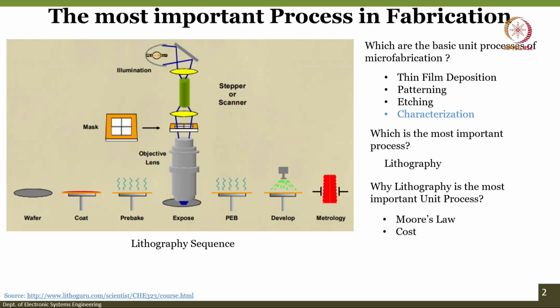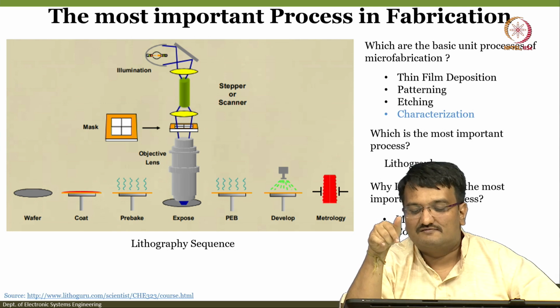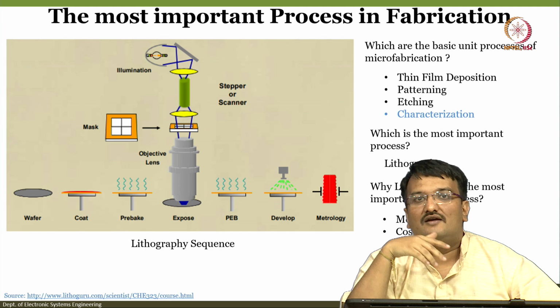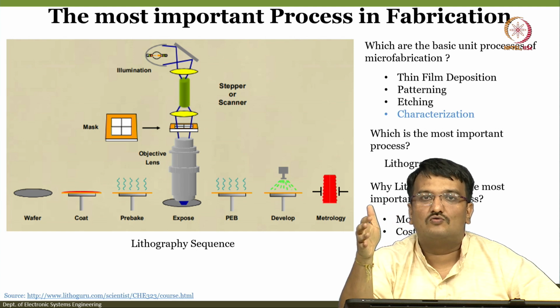lithography. Another important point: I mentioned that these are all micro and nano structures, even smaller than our hair size. A minute difference can result in a defect. Let's say you have a very small defect in your mask, a possible short, where you want to make an electrode which should be a different electrode. A possible short in your device can completely defeat the purpose of your development. Now, if there is an issue in your mask, it will get reflected 100 times in your wafer, so all your devices will be faulty. Ultimately you have to recall the devices.